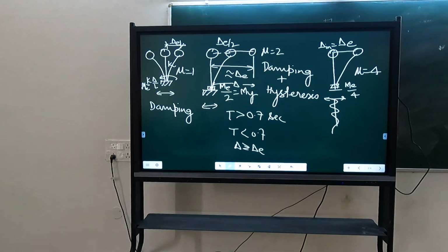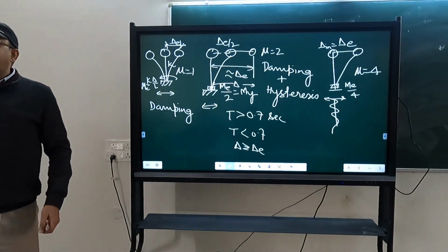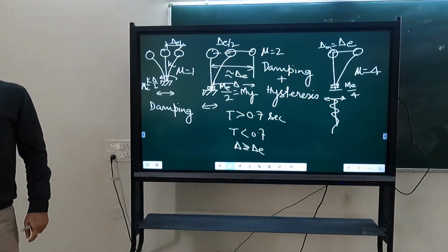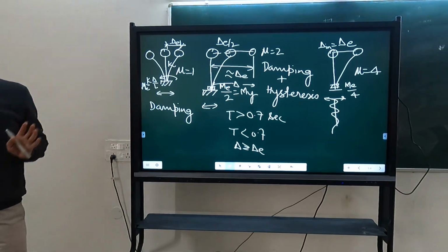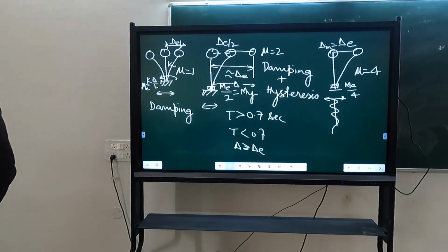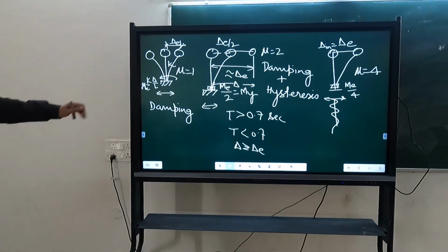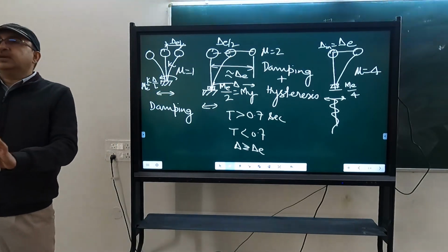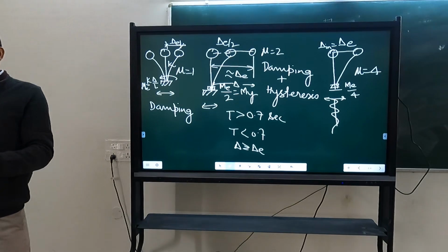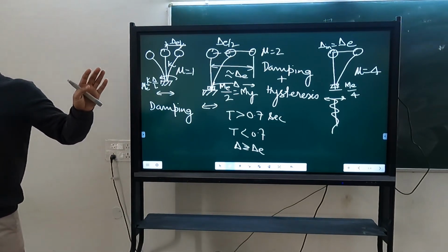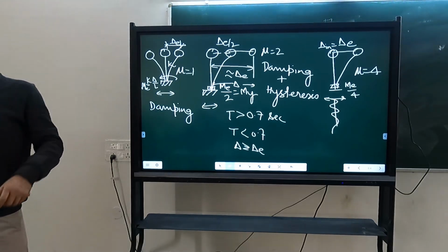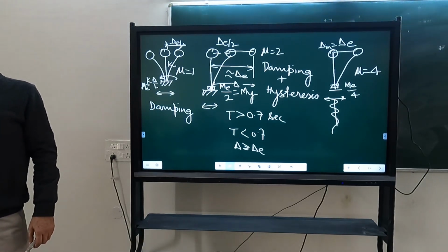No, it was not. It is elastic. Earthquake, whatever earthquake is causing, the maximum displacement which is occurring in the earthquake, there is no failure. Whatever maximum displacement is occurring during earthquake, that is delta E. Okay. Up to delta E, that section will go up to LE. Here there is no section. Think it like this. I have a section where strength can be anything. Whatever strength you will say, I will provide. Okay. And I am shaking it during earthquake.